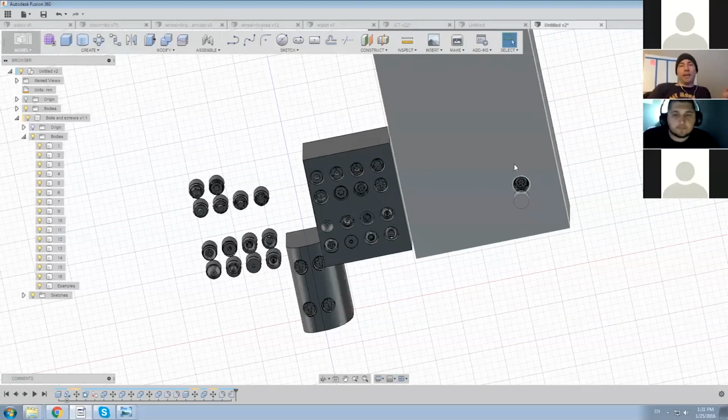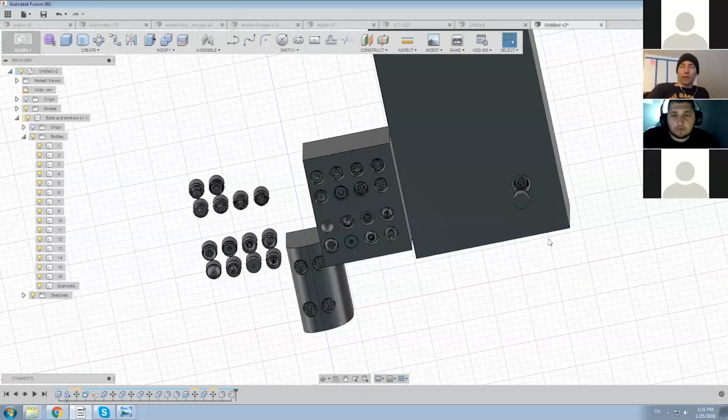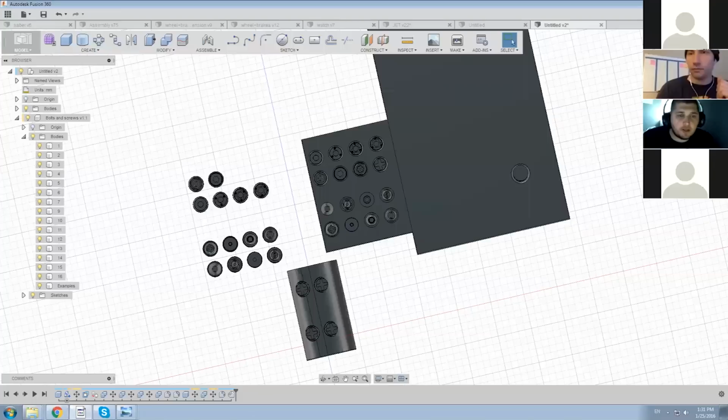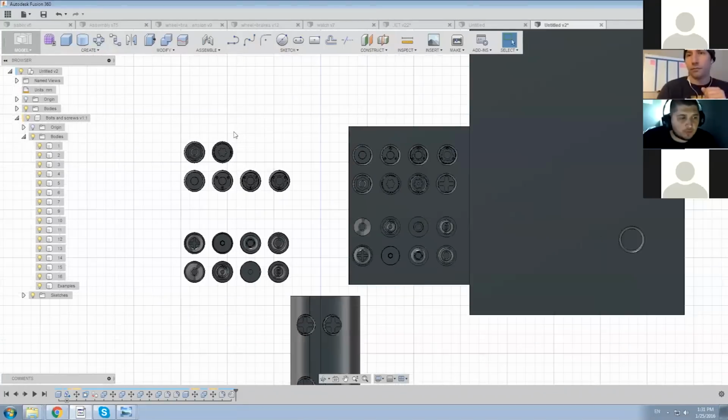So you go STL file when you bring your stuff into ZBrush, then? Yeah, that's my usual workflow. Okay, and that keeps your detail pretty good. Yeah. If anything, one trick would be, let's say you want to preserve some sort of hard edge, you need to import the STL and then Dynamesh it at a very high resolution.